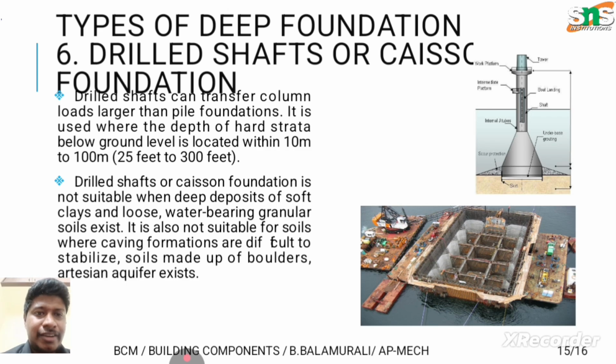A drilled shaft foundation is not suitable where deep deposits of soft clays or loose water-bearing granular soil exist. It is also not suitable for soils where caving formations are difficult to stabilize, or soils made of boulders and the like.